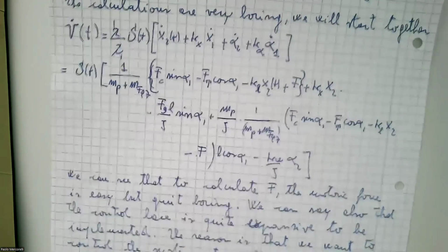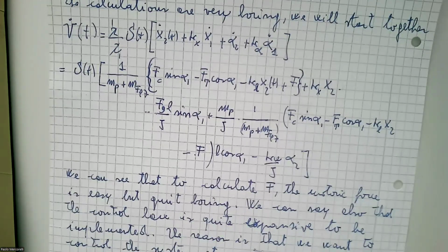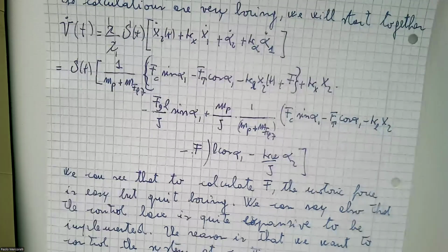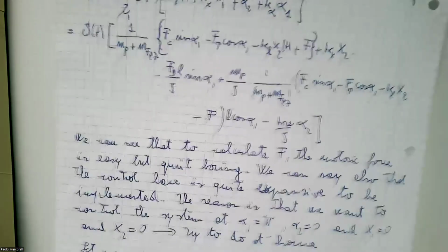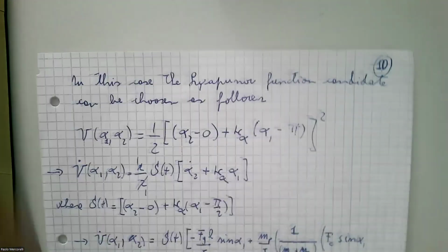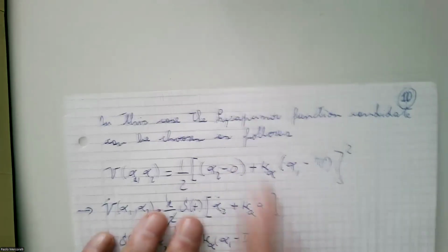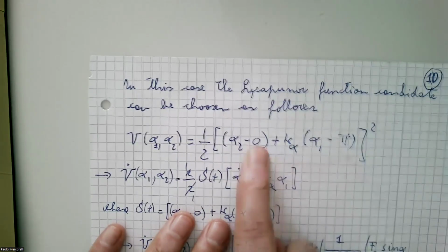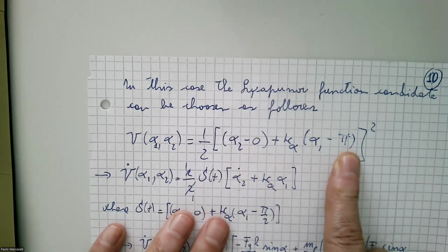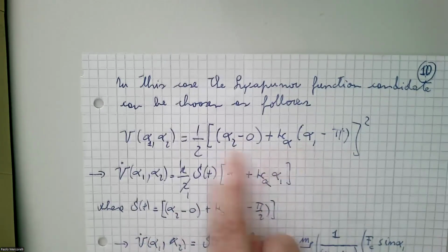The problem is here I cannot run because I stabilize also the car. What can we do to run? Typically, we define, let me show you the last slide, a Lyapunov-like function, which consists of stabilizing just the vertical position of the arm.